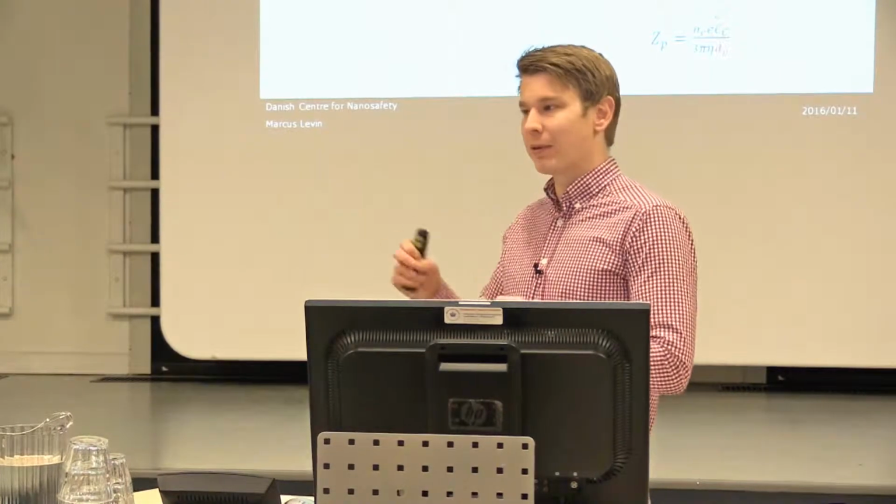I have mainly been working with unipolar charging, and now there's some equations here, but the important thing here is that if we do this, then we should be able to link the number of ions with the particle size, so that if we then measure this, we can always link it to a particle size. And this is a fundamental thing in measurements, that we condition it somehow, and then we should be able to link that with the particle size.